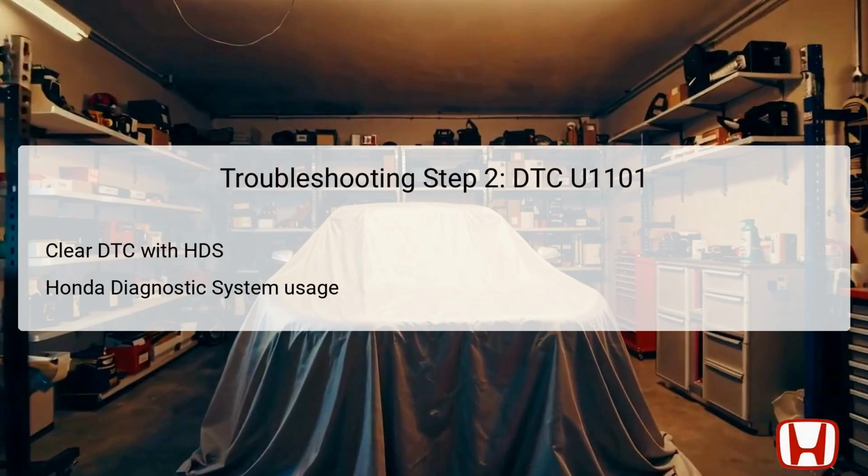HDS is a specialized tool used for vehicle diagnostics and has capabilities that allow technicians to reset codes and clear fault memory stored in the ECM. Clearing the DTC ensures that any transient faults are eliminated from the ECU's memory, allowing the technician to assess whether the issue persists. If the problem recurs after clearing, it signifies a deeper, likely persistent malfunction within the FCAN system. Thus, utilizing the HDS is critical for accurately resolving DTC U1101 by confirming whether it is a permanent or intermittent